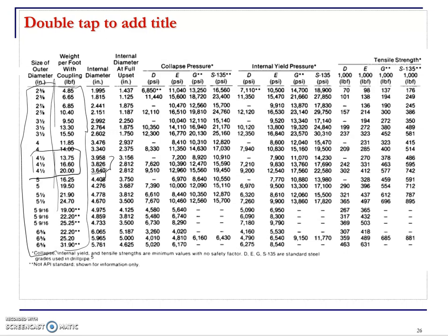The smaller the inner diameter with the same outer diameter, you have a heavier pipe because you have more steel there, right? So the internal diameters are different, but usually when we report these drill pipe sizes, we talk about the outer diameter and weight per feet, and then you go and find all other information about this pipe from these types of tables.